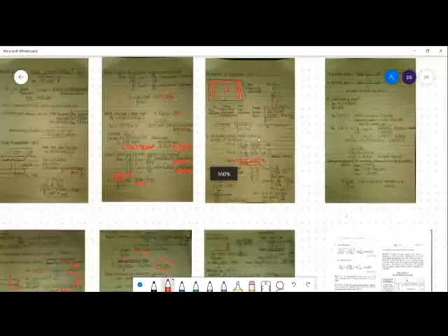And we compute the provided development length. So for long direction, 4,800 minus 2 times 75 concrete cover minus 600. Why minus 600? Because we subtract the column, over 2.